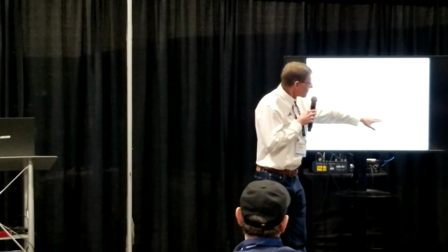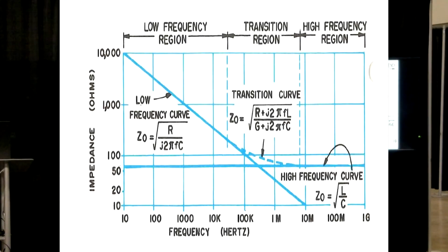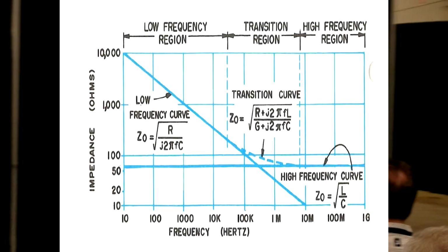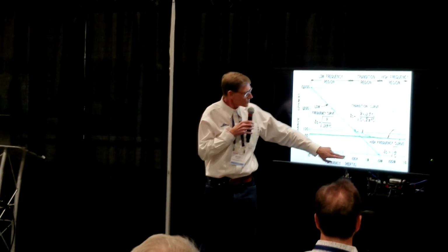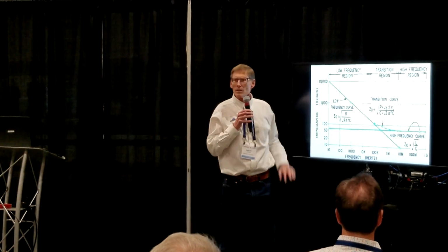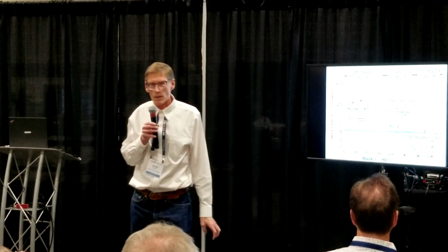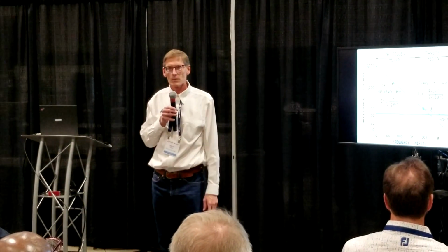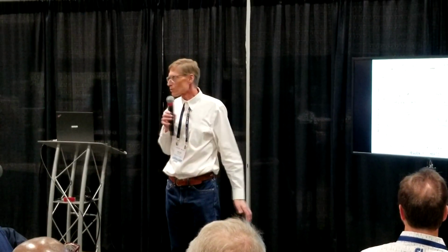When we start going down in frequency, we notice something. And this affects our audio hobby quite a bit. What the hell with this? This is our impedance through our audio frequency range. This is 10 hertz, 10K, 100K, but look at this. Is anybody aware that the impedance of your cable at audio is going up like that? What's your impedance of your loudspeaker? 4 ohms, 8 ohms, up maybe 16 ohms, right?